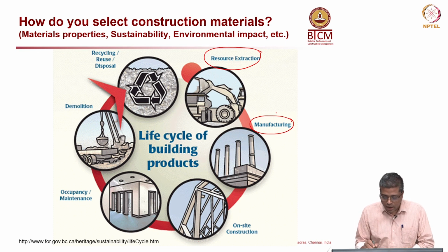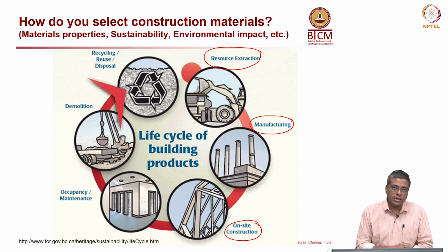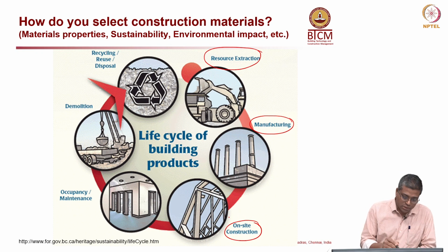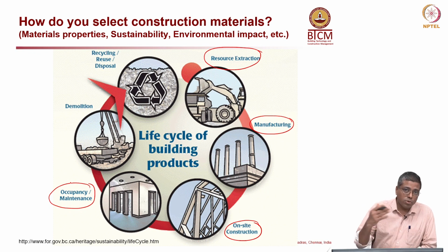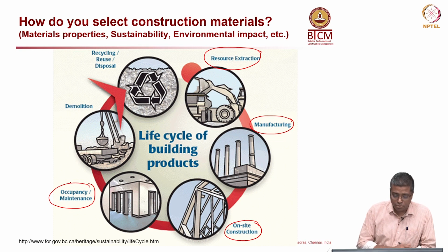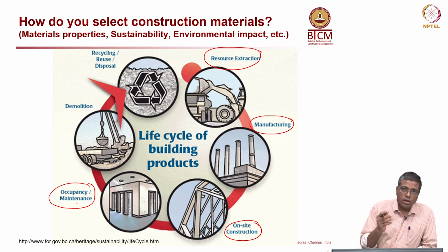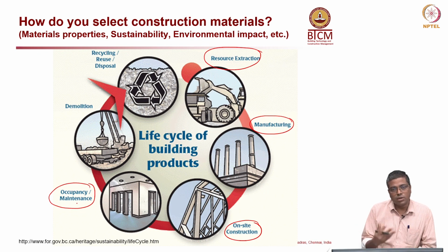You make concrete, and after that you use that material at the site, and then during the occupancy, the material is exposed to the external environment and also the structural loading. So both mechanical and environmental loading are important during the occupancy. Because of mechanical loading, the structure might start cracking, etc., and during the environmental loading, it might have some chemical actions on the structure, which might lead to some deterioration, which might eventually weaken the material. So it will also get cracking, etc., or deteriorate.